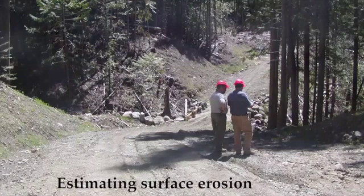Based on all available literature dealing with gravel roads, we have come up with some simple tables that consider road surface sediment generating potential, road slope, and amount of traffic to estimate the amount of surface erosion one might expect from any road over the course of a year. These tables are incorporated into the calculations that estimate road surface contributions to fine sediment generation.